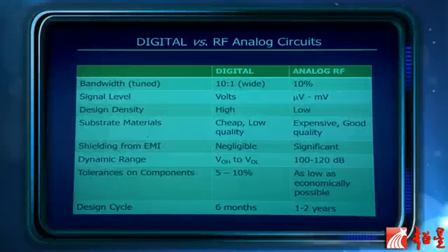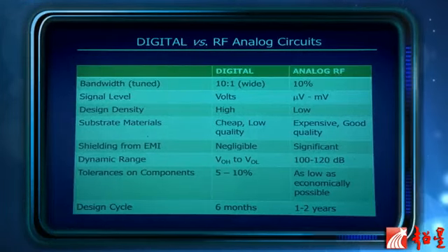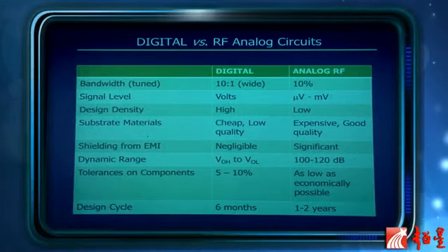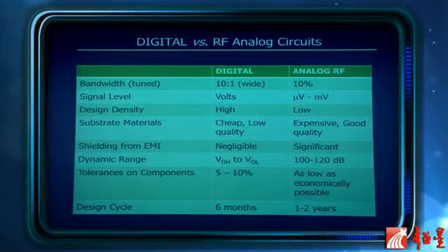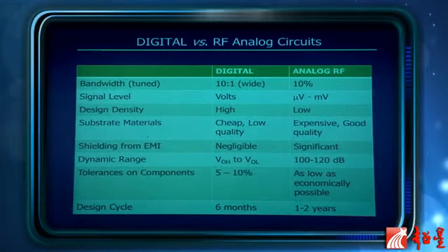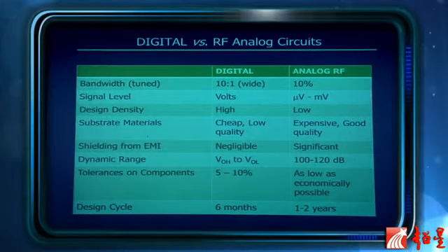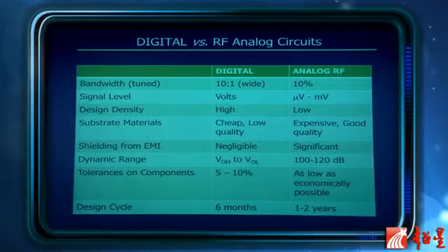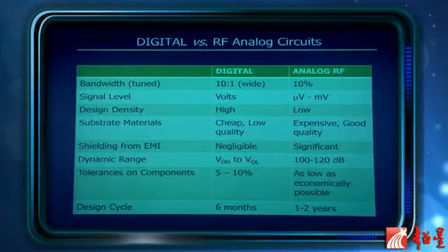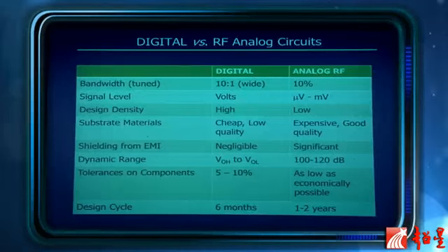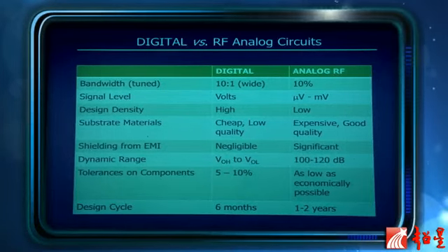All right. So what's the difference between digital design and RF analog design? Because RF engineers have been concerned about high speed as well, right? Because in microwave design, they're all very high speed signals. And this is the difference. First difference is about bandwidth. RF design usually has very small bandwidth. Most likely it's just one single sinusoidal waveform.